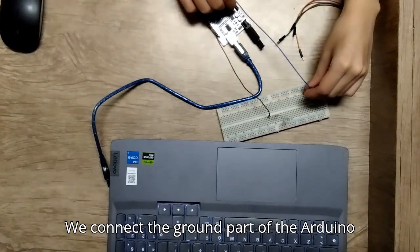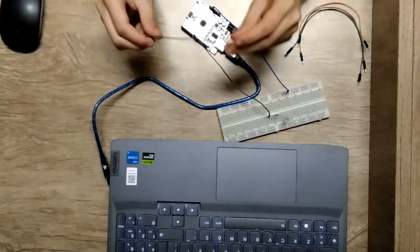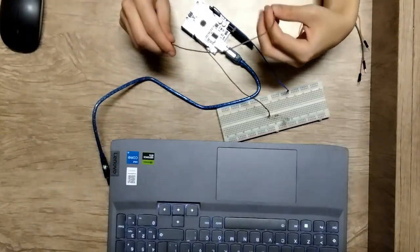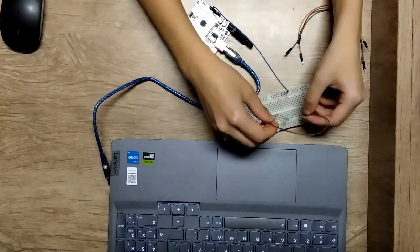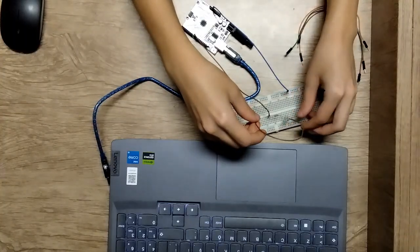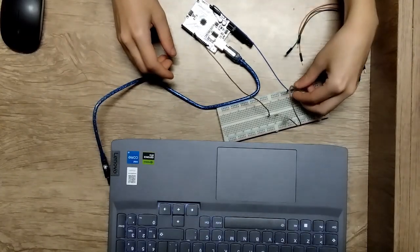We connect the ground part of the Arduino to the breadboard with a jumper wire. We connect the free short leg of the LED to ground.